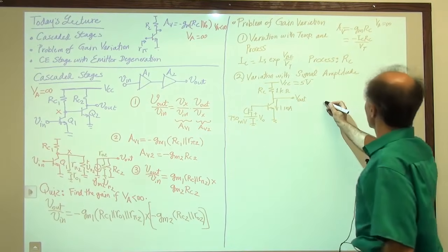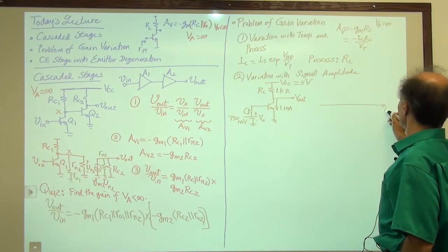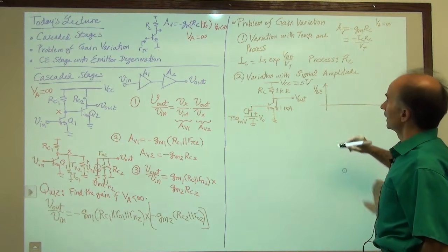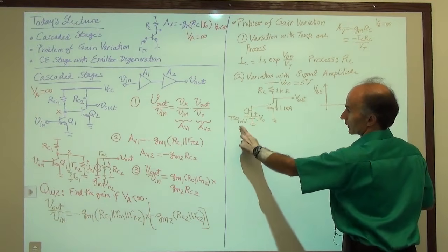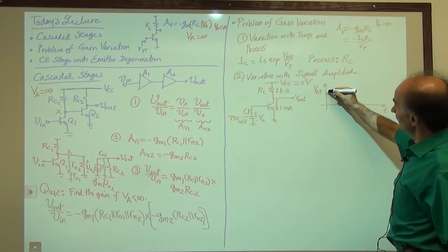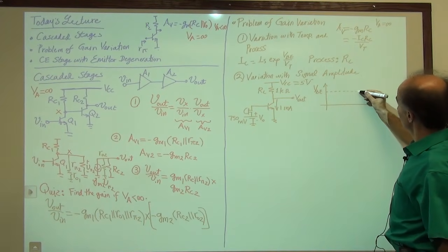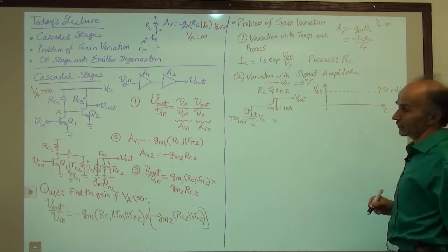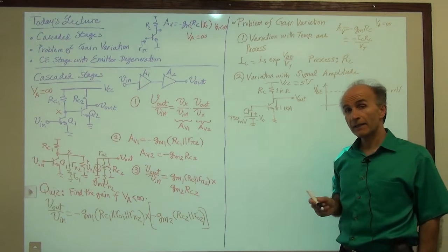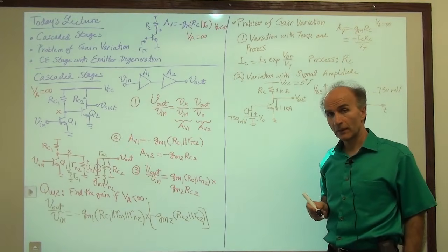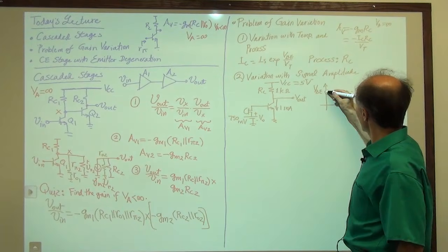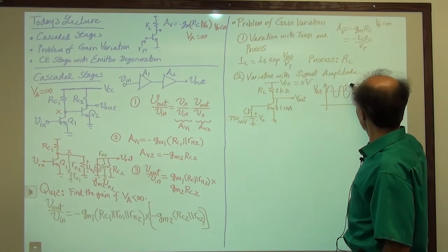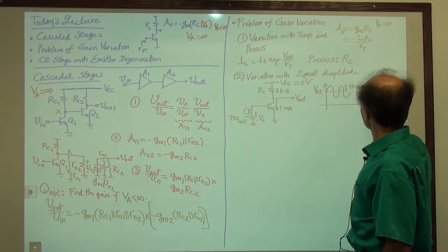Okay, so here's what we have for the base emitter voltage as a function of time. So VBE. Without the signal, when this voltage is 0, we have 750 millivolts here. And now the microphone signal comes in. And let's say the microphone signal is not that small. In particular, I will assume that the microphone signal is a sinusoid with an amplitude of 18 millivolts.